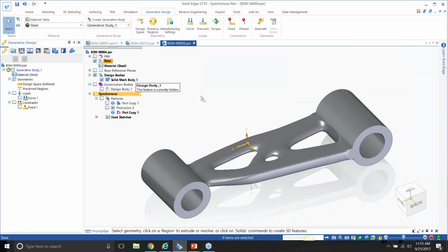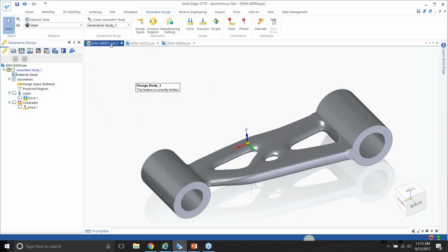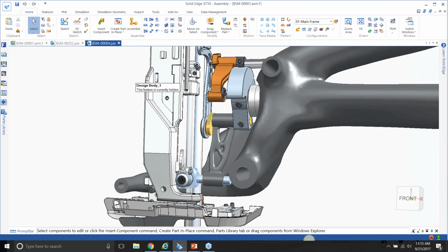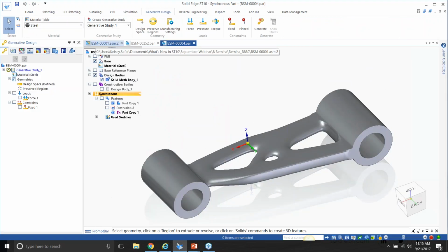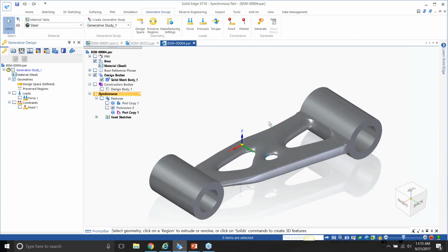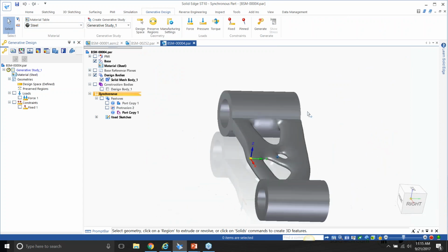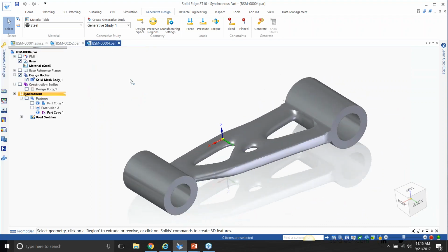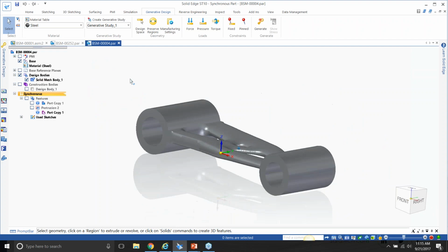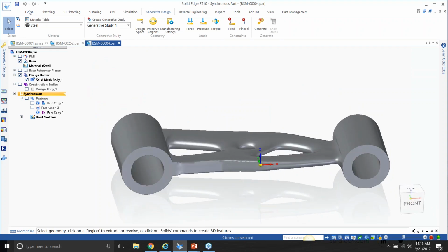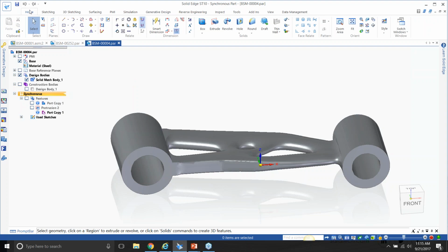And just click yes. And going back to assembly, we can see that it's perfect. It looks really nice. And just like that, in a matter of, well, a little bit more than 40 seconds, we decreased our part weight, and we made sure that it's still pretty safe. It's relatively safe. But say, like I said, this was a mesh body. Say we wanted to design it and kind of edit it like a B-rep surface. Due to convergent modeling, Solid Edge allows you to do that.